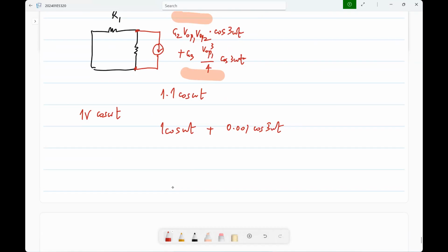Okay. So what this whole thing allows you to do is to calculate something, right? We had nothing, which is linear analysis, or swing limit, which simply says you can't apply a signal larger than this, then you will be finished or something like that. This one at least tells you if you want your harmonic to be less than, let's say, 1% of your fundamental amplitude, what should be the signal amplitude?